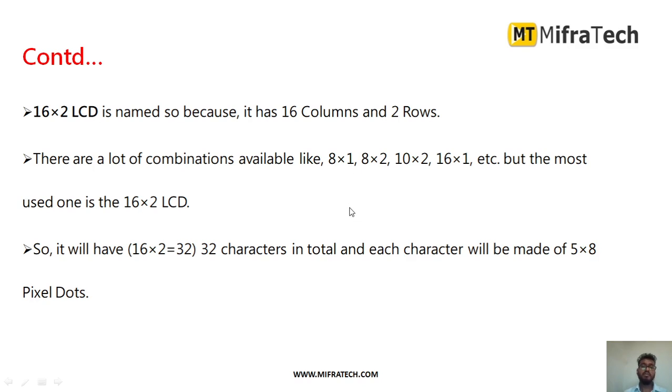There are a lot of combinations available, such as 8x1, 8x2, 10x2. But generally we mostly use the 16x2 LCD display only. As it is a 16x2, there are totally 32 characters you can display in this 16x2 LCD display.